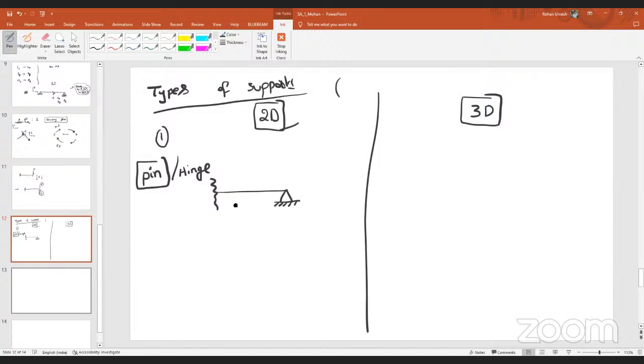First of all, why are the reaction forces developing at this point? Let us say I'm talking about the XY plane. Can you tell me what reactions are possible? Forget about the direction right now, upward, downward, left side, we'll discuss that in detail. There might be a reaction force that will develop along the Y direction, and also a reaction force that will develop along the X direction.